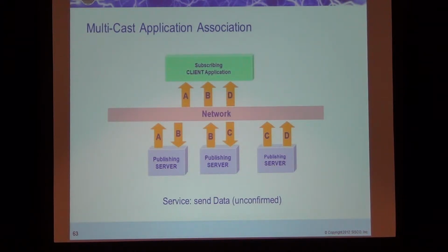So you're not waiting for SCADA type scans to occur to decide, well, I see the current flow is starting to increase in a particular bus, perhaps I need to start making adjustments. No, we're talking about things that happen in milliseconds for protection, so that you can implement blocking, interlocking, and things of this nature right down into the devices and fundamentally replace the hardwires that are so costly to build into substations.